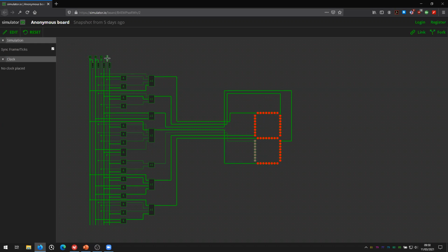That's a 9. If I go above 9, then the behavior is actually undefined because we didn't include that input in our table. So we actually have no idea what's going to happen. So for intents and purposes, we're limited to 1100 as our kind of top. In fact, 1001 is 9. So just 1100 happens to show a 9. But actually 1001 is the top input. So yeah, that's how to design a digit display.